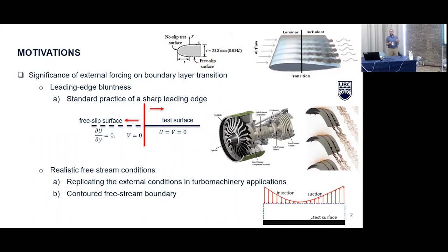And so we study this, and oftentimes we study it using direct numerical simulation where we make a very gross approximation of the inlet conditions of the flow. Generally, in the context of fundamental DNS simulations, we impose a pressure gradient on a flat plate. And the flat plate acts like a proxy for our blade suction surface. And the pressure gradient is imposed either using a boundary condition or a contoured wall. And that gives the representative conditions, and we can add turbulence, we can do all kinds of things to also look at the transition in a more realistic way.